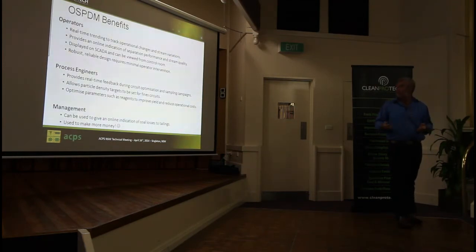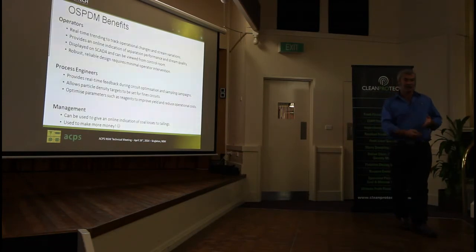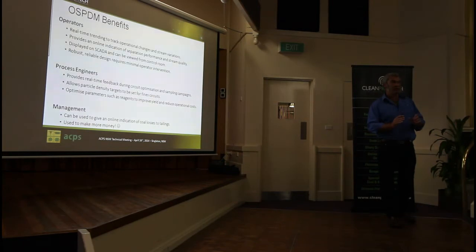And once you've got that info, coming out, particle density and solids concentration, what can you do with it? As an operator, as a process engineer, you can change things in the flotation. Change the collector, as I said, change the froth. Do what you want, change the froth depth, and you get the response immediately. What's actually happening? If the plant feed changes, you'll see it. It comes up. Yeah, and that's just on the tailings line.